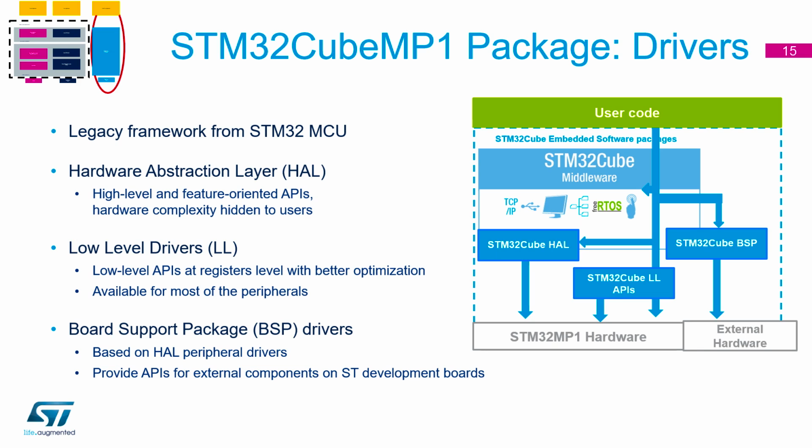If you've got add-on shields like the X-Nucleos, so you've got the Arduino connectors on the bottom of the board, you can use any of the board support drivers that we've written for them. So most of our devices have got board support packages. So if you're using a MEMS sensor, you'll want the driver for that MEMS sensor to communicate through SPI or something like that. So all of those software is available. And then your existing user code will be talking through a defined set of instructions or APIs. So any user code you've written can all be reused again inside the Cortex-M side of the MP1.